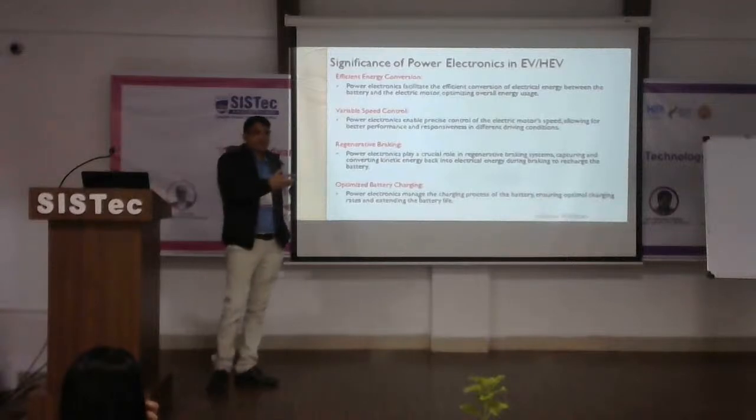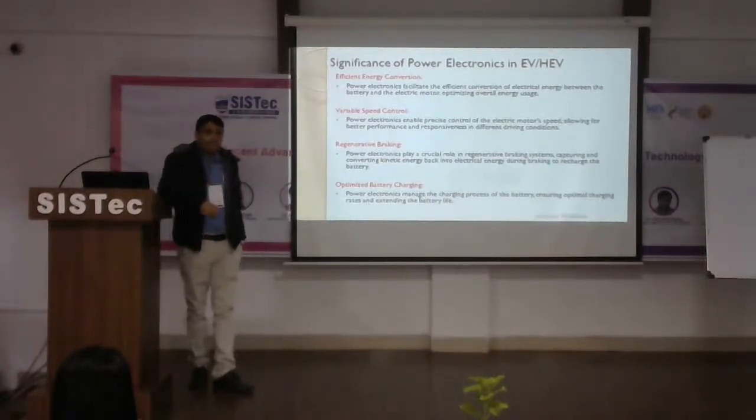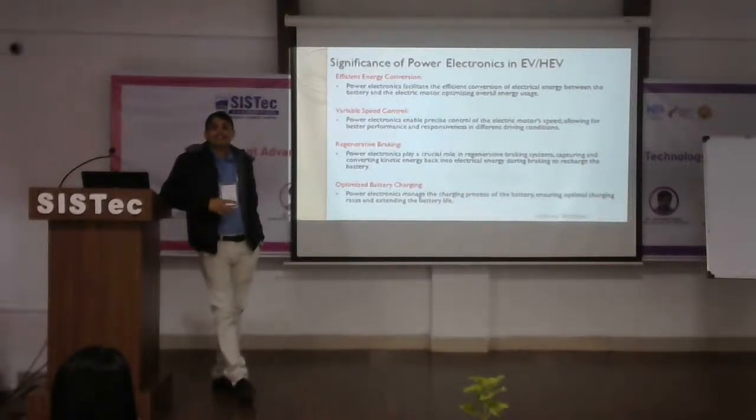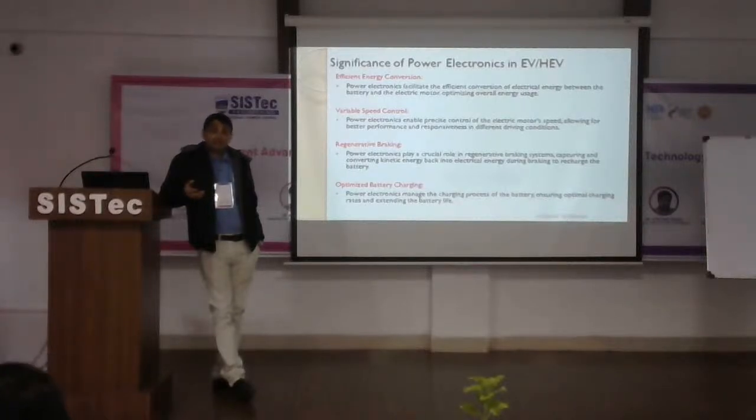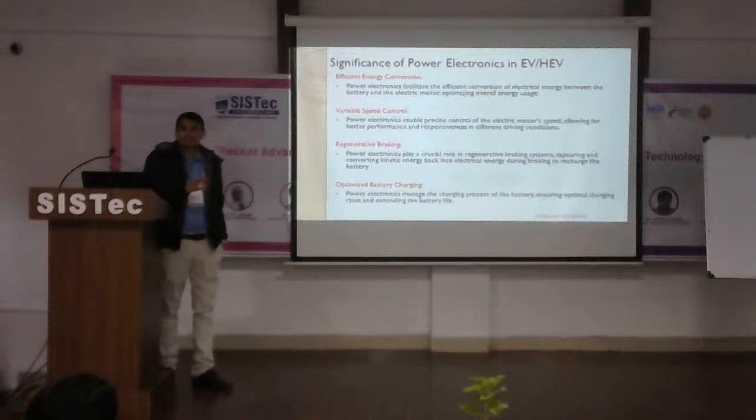As you know, we discussed a little while ago that the motor will be supplied by the battery. But when you generate power by the same motor, that power will again be fed to the battery. So we will require a bidirectional converter. That bidirectional converter will provide supply to the motor, and if you need to store that power, the same converter will be used to store the energy generated by the motor in the battery. So that is the benefit. And yes, a bidirectional converter is required.